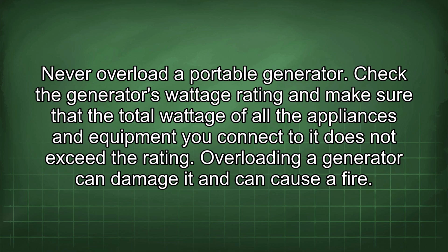Check the generator's wattage rating and make sure that the total wattage of all the appliances and equipment you connect to it does not exceed the rating. Overloading a generator can damage it and can cause a fire.